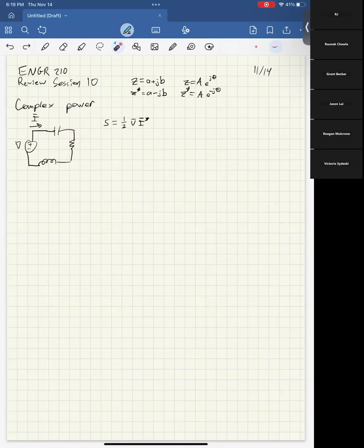Resistors, all they can do is resist, so they always dissipate power as real energy, turning it from electrons moving into heat. But capacitors and inductors do something different. They store the energy in some form. Capacitors store it in the electric field, inductors store it in the magnetic field. While that isn't dissipating the power, it is storing it, so it is removing it from the circuit. We model the combination of those two as complex power.